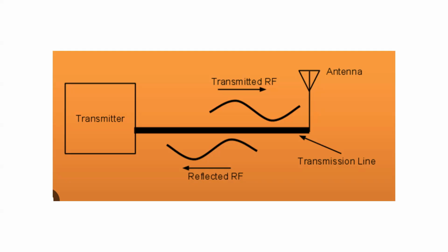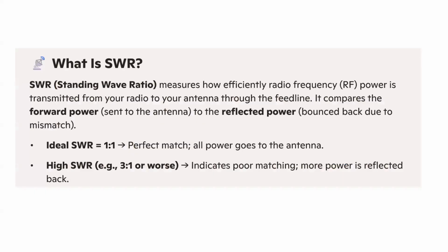All right. And it took me a long time to realize this, but this reflected RF does not disappear. And it doesn't necessarily heat up your transmitter. It actually gets reflected back down the line and it just keeps bouncing until it's absorbed. So there's things about SWR that keep hams talking, and they don't always agree about their understanding of SWR.